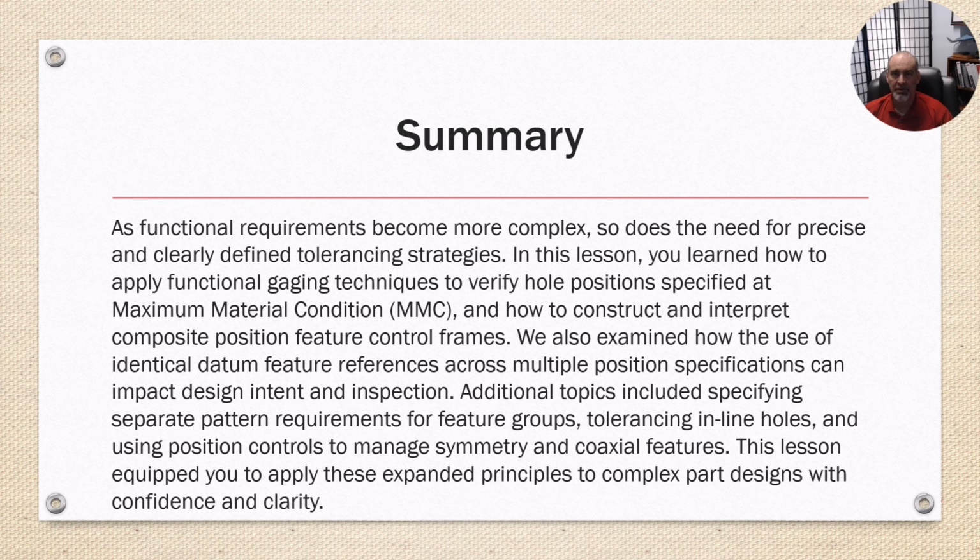We also examined how to use identical datum feature references across multiple position specifications and how they can impact design intent and inspection. Additional topics include specifying separate pattern requirements for feature groups, tolerancing inline holes, and using position controls to manage symmetry and coaxial features. This lesson equipped you to apply these expanded principles to complex part designs with confidence and clarity.